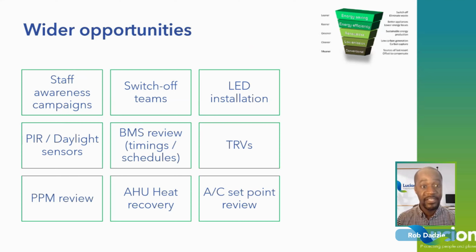So LED installations, building management review, looking at timings and schedules, PIR, which is passive infrared systems for lights. You know, don't just install LED, install PIR, so that if there's nobody in that room, those lights will automatically dim, or implement daylight sensors. Low cost initiatives such as staff awareness campaigns also sought. And can you implement, you know, heat recovery associated with your air handling systems?